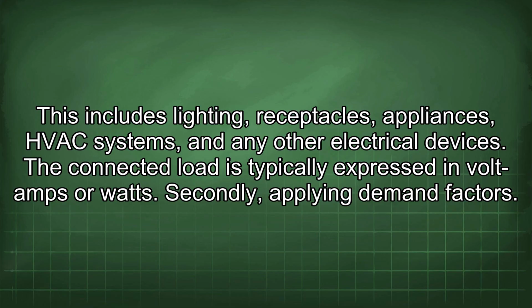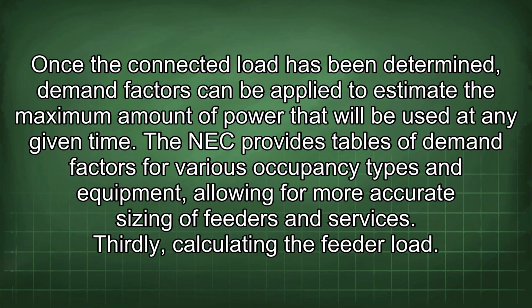Secondly, applying demand factors. Once the connected load has been determined, demand factors can be applied to estimate the maximum amount of power that will be used at any given time. The NEC provides tables of demand factors for various occupancy types and equipment, allowing for more accurate sizing of feeders and services. Thirdly, calculating the feeder load.